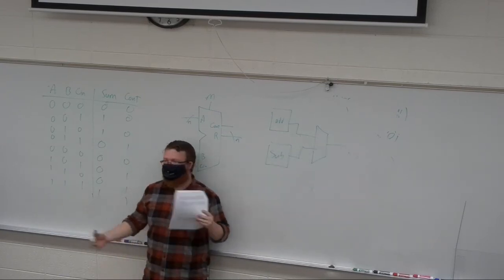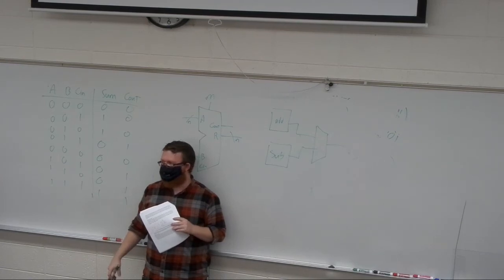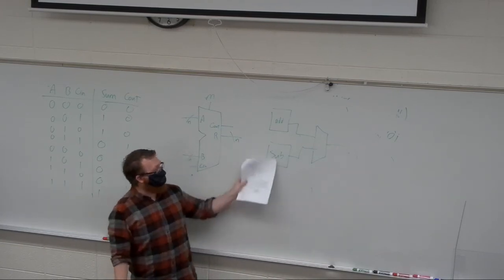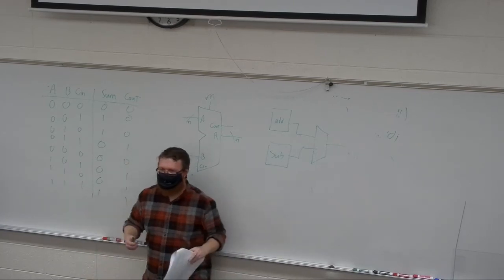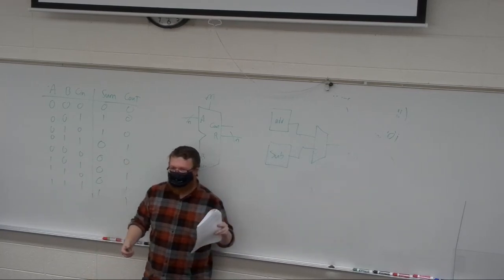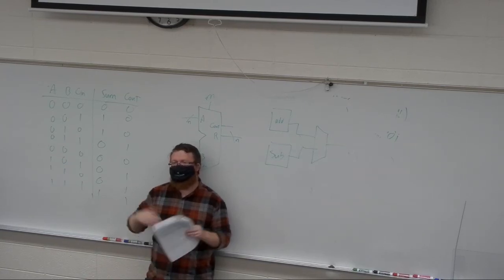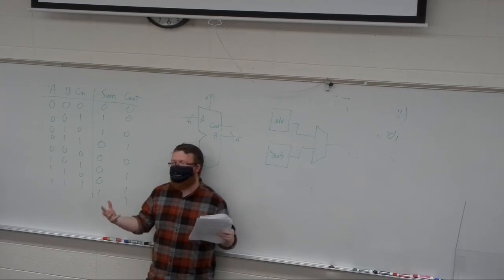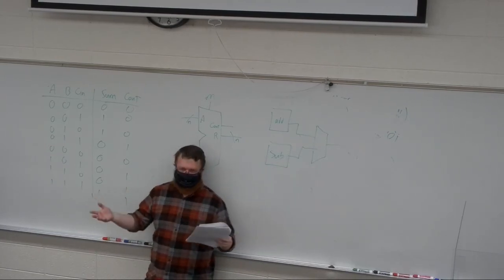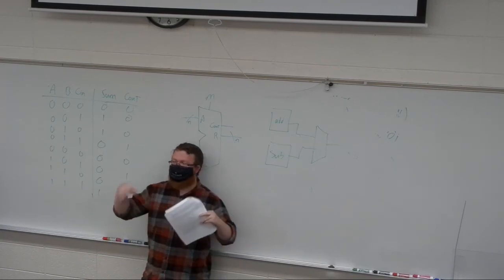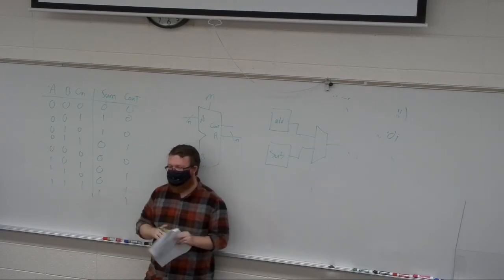Does anyone see the obvious downside to doing it this way? What's a potential downfall? Power. I am doing the add, subtract, and every other operation all at the same time. So no matter whether I want them or not, they're consuming power. So you could build up a more complex logic that saves power, but then you're adding space, right? So only add if, so on and so forth, but it costs space to do that.